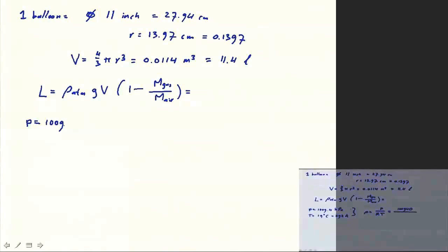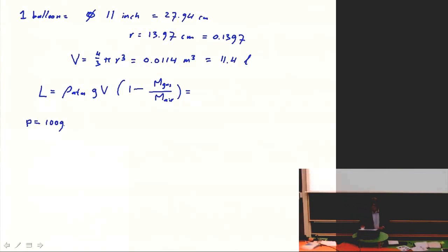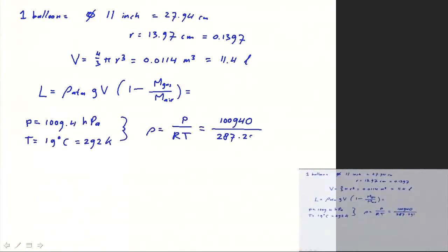The R, which R do we need here? The 8.31 or the 287? 287 is indeed the one we need. And the temperature, 292.